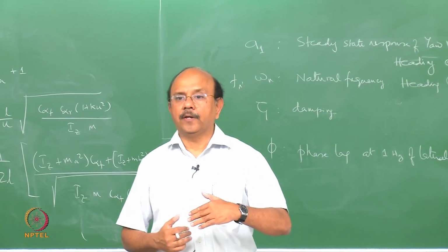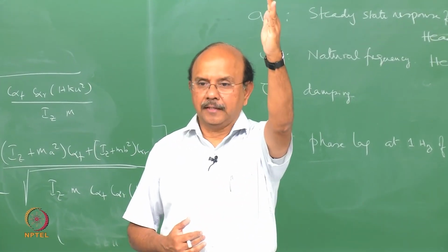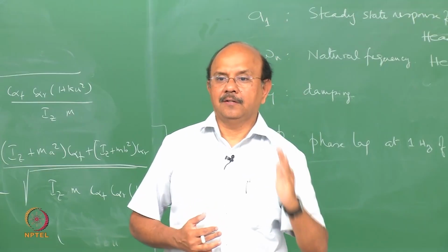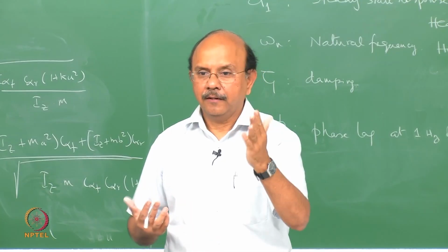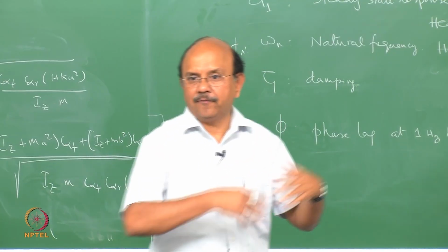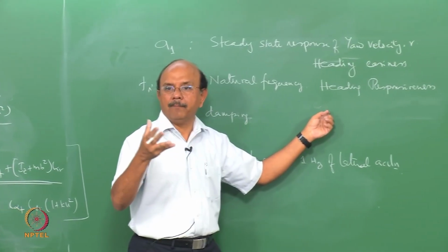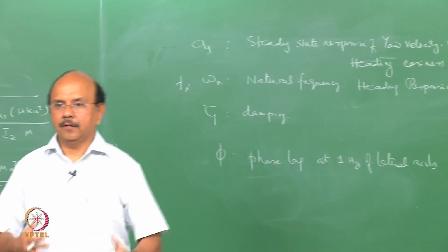Larger the omega n, smaller it is. Smaller is to say, for example, the peak time. So smaller the peak time means I will reach what I want faster. So it's ease with which I will go, or response of the system is now better when omega n is increased. Right?